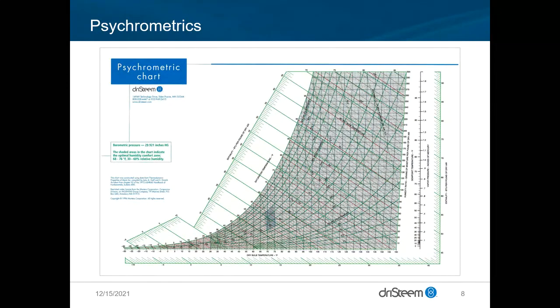Let's move on to the actual physics and psychrometrics of humidification. I'm sure most of you are familiar with the psychrometric chart, but we're going to go through the basics of it here real quick. It is a very important tool to help show the path that air takes during its travels from the outside to where it's being supplied, breathed, used for keeping equipment in good condition. All the reasons that we have ventilation requirements and design set points in space. So there's a lot going on here.